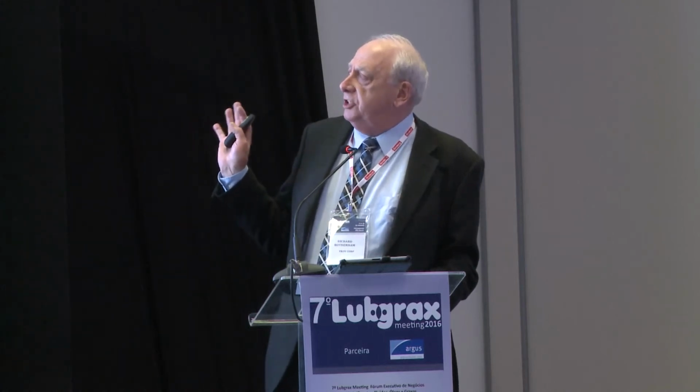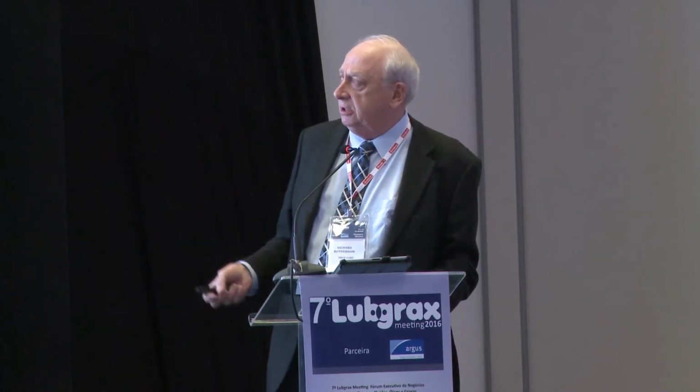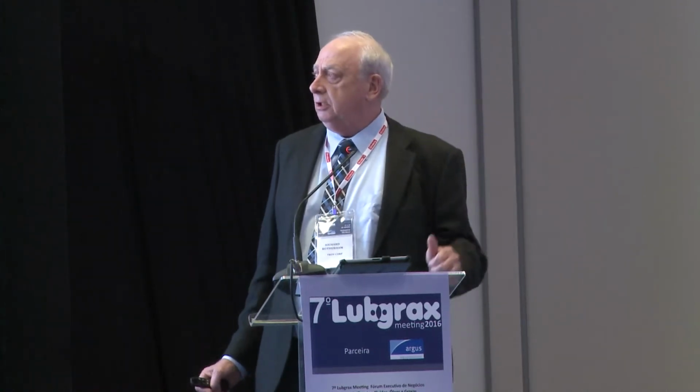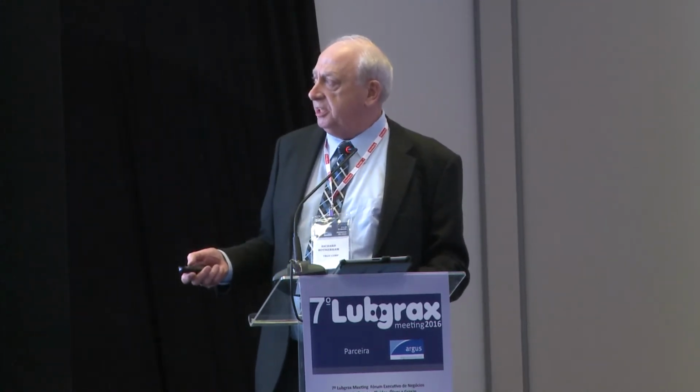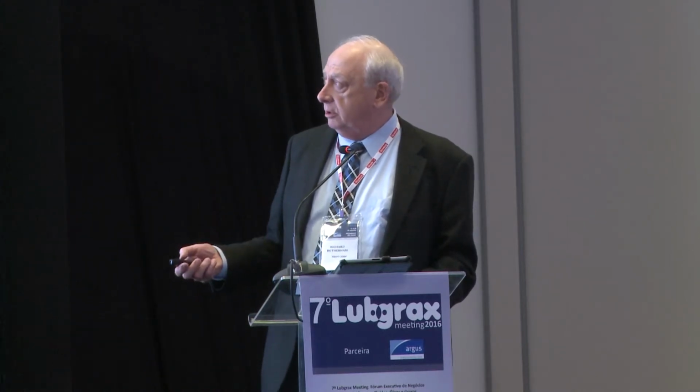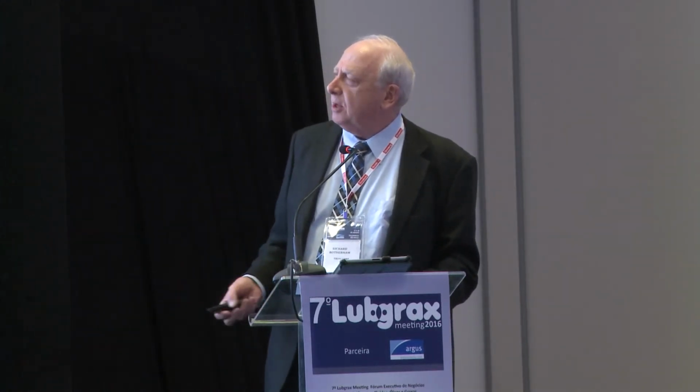pH, different fluids have different optimal pH ranges. So as bacteria grow and produce acids, as we've talked about, the pH can fall. So the fluid pH needs to be kept in the recommended range. Some fluids are designed to be used within higher or lower ranges.